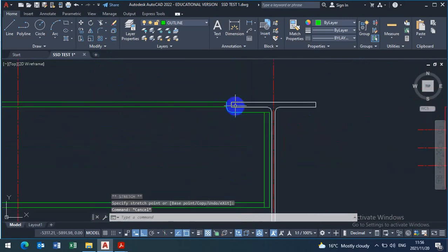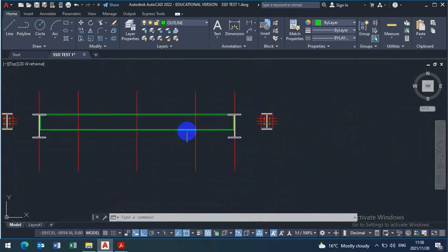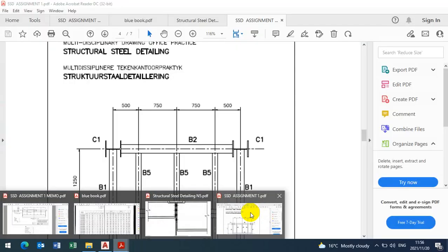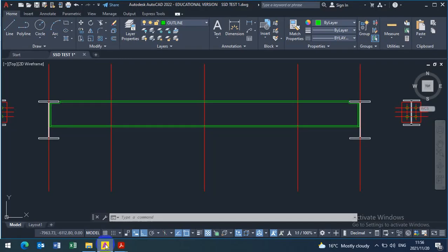Once that has been done, you have put the notch. You need to show the hole position. Remember what's happening here. We are not looking from the top, we are looking on the side view. So we'll see the hole position for this beam that is coming here. The beam that is coming here is this beam 5, okay, beam 5 coming from the top side of beam 3, but we are looking from the side view, so we'll see the beam as it is sitting on the center line here, on the flange. It's sitting on the web of beam 1. It's here. So what is that?